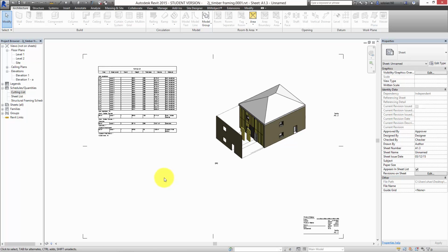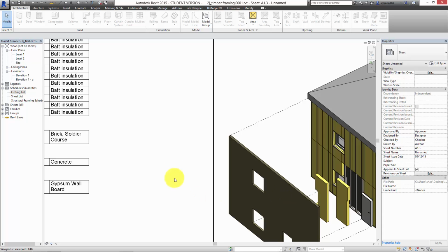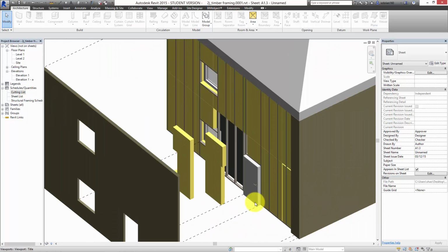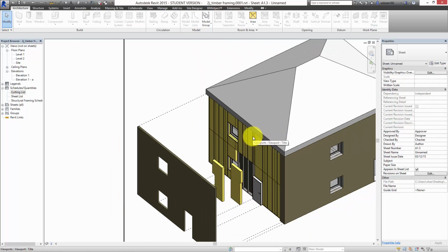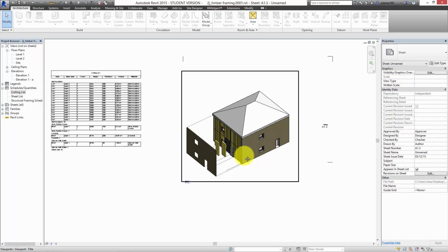So you can see that if you just worked on this for a while, you could make up a schedule that has all the cutting list regarding the bad insulation, but also you can make up a schedule regarding the timber frame structure, any of the structure in the building, and you can have it all on the same sheet, including an exploded isometric drawing. And it's a very, very nice way of just describing the entire construction without getting into the actual key junction details. Yeah?